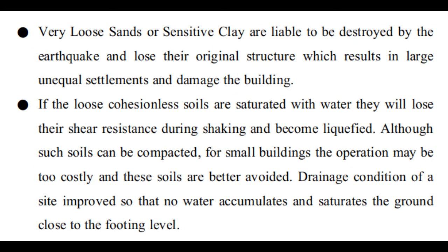Very loose sands or sensitive clay are also liable to be destroyed by the earthquake, and they actually lose their original structure, and that results in large unequal settlement and damage to the building. So you have to take care which type of soil the site has. If loose cohesionless soils are saturated with water, they will lose their shear resistance during shaking and become liquefied.